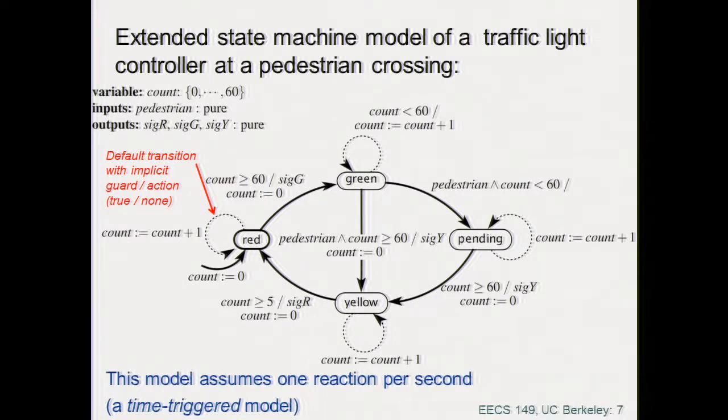As per this model, how can we ever have count greater than 60? Because there may be an error, for example. In this situation, you can start with the counter which is larger than 60. But we always have that initial state where count is 0, because I told you that was the initial state. That could have been another state, in principle. And you always put larger or equal than just to make this sure. So, in fact, if I start from there, it can never go above. But sometimes you put that too, also because there may be a misreading of the sensors. And so it should be 60, but it's 61. So you don't want to stay there forever. So you say, as long as it's larger than 60, get out of it.